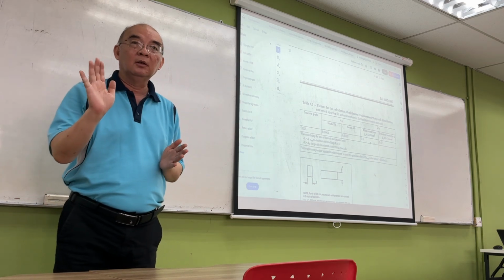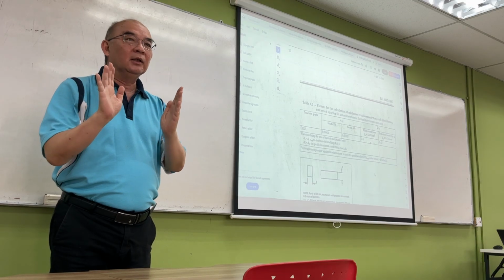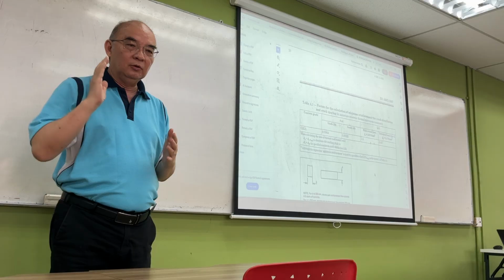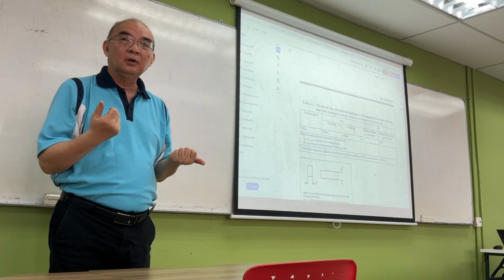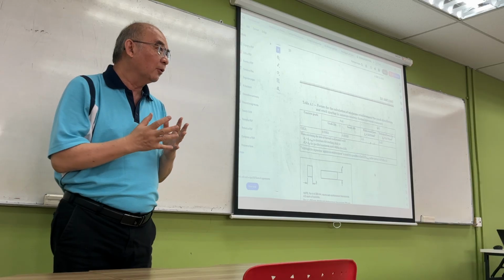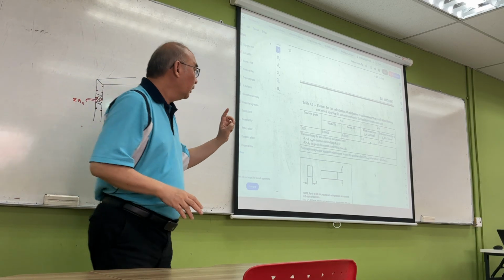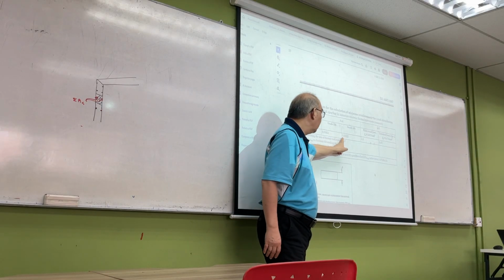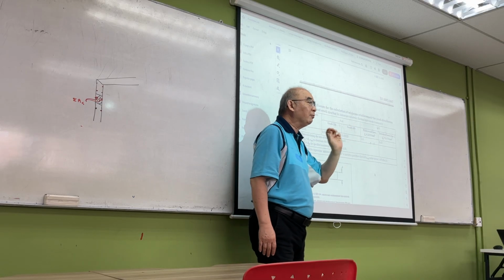This is for water tank crack control, which is much more stringent. The reason it is much more stringent is because if water seeps through, it can cause corrosion in the rebar and so forth. That's why for the water tank, the reinforcement for crack control is higher, 0.35%. It's 0.0035, that means normally I call it 0.35%.